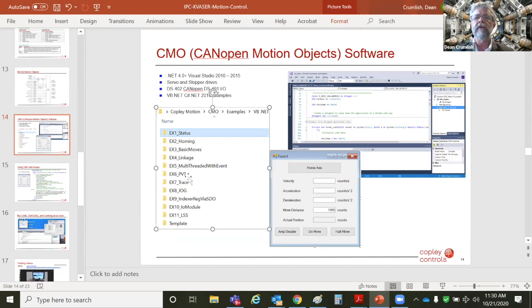And this is all done on the computer. You may have a wave that you want to generate, like a heartbeat, or move in a way to create a wave, and you have your own path. So you can create a path using a PVT, and we'll do the polynomial cubic spline interpolation in the drive, and we'll be at a very deterministic position once every 250 microseconds, plus or minus a microsecond, across a distributed network. So very accurate. If you know your path ahead of time, you can definitely stream it out and do multiple axes of coordinated motion in a very efficient way.